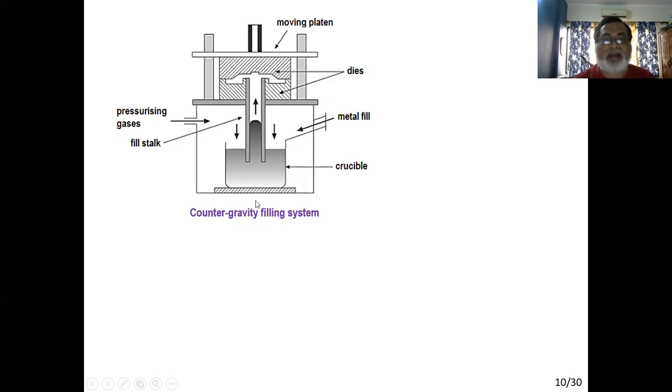All the time, liquid metal moves only as we allow it. So velocity is solely under our control, and depending on the alloy, we can increase or decrease the velocity of the liquid metal. All the time, it is moving against gravity at a very low speed.